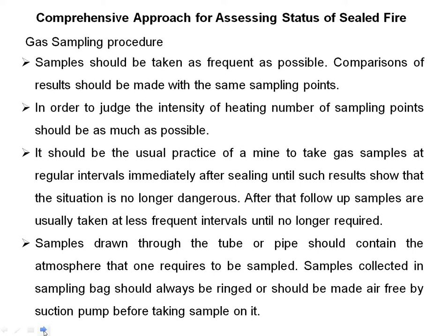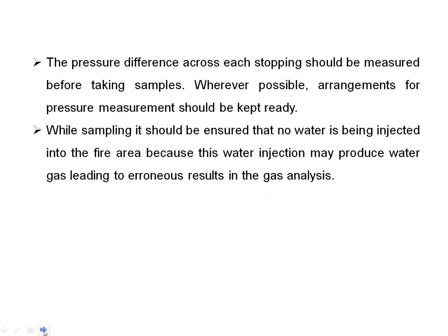So you see, this is also a most crucial thing, and that is the most important thing for sampling procedures. The pressure difference across each stopping should be measured before taking samples. So wherever possible, the arrangements for pressure measurements should be kept ready, as the pressure difference across each stopping should be measured by whoever is taking the samples. All arrangements should be kept ready.